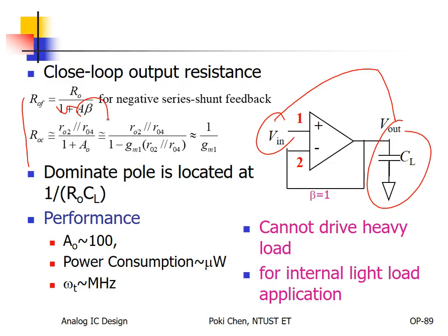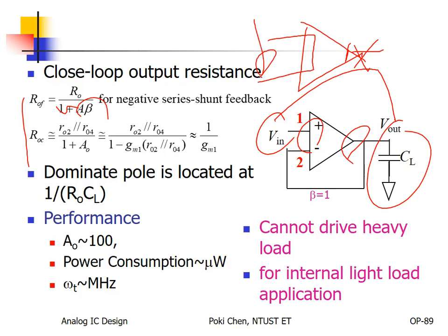You can increase the input resistance for this. You can decrease the output resistance for that. But if this is not an op-amp, for example, that is some kind of current amplifier, then I promise you, you can decrease the input resistance and increase the output resistance. What does it mean? What do you want? Almost all of them will be enhanced by such kind of negative feedback.